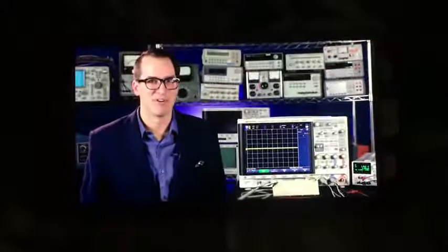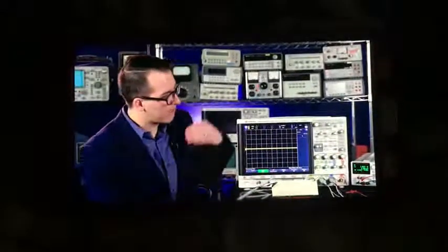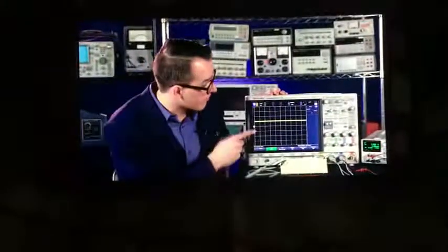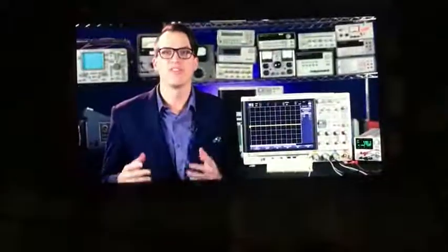So let's take a look at an example. I have a resistor hooked up to my power supply, supplying a constant 5 milliamps of current, and we're going to see how much work my power supply has to do, how much voltage it's going to apply to get 5 milliamps of current through this resistor. And it looks like it's about 1.1 volt to get 5 milliamps through this resistor. Voltage, current, and resistance all behave according to Ohm's law, which we will cover in a later video.